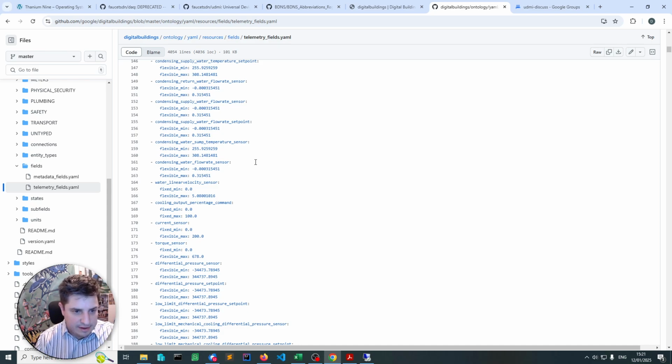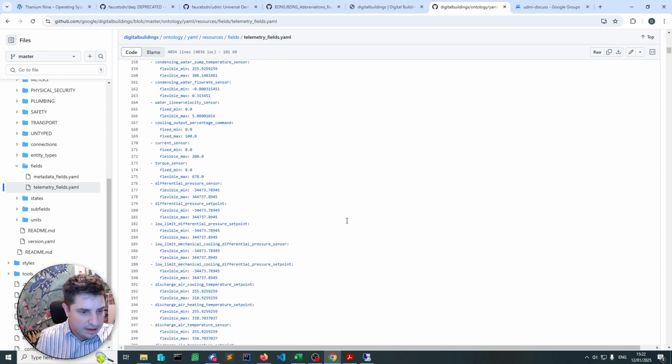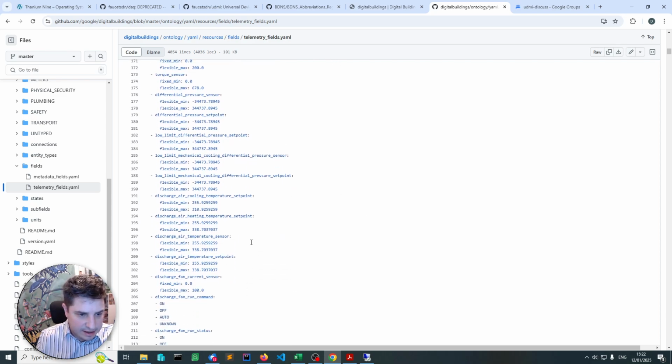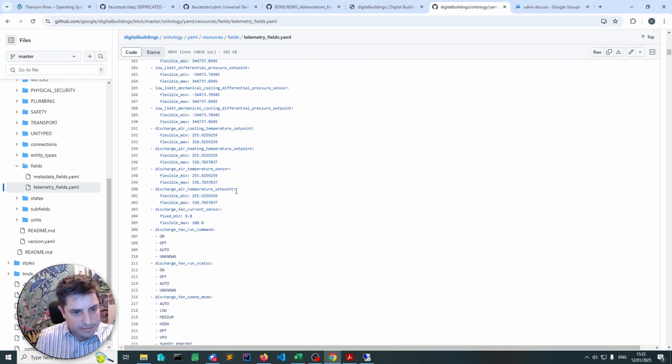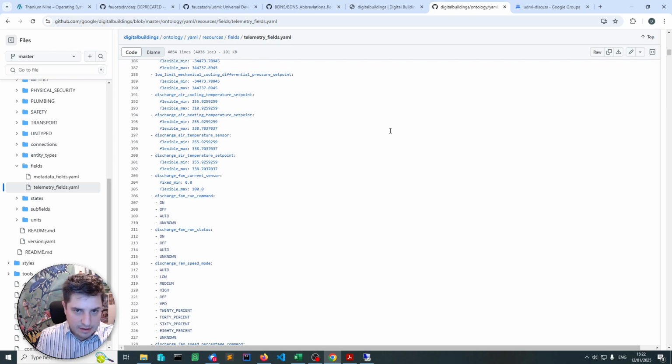Lots of different BMS companies typically have their own methodologies around point naming, and when we want to apply machine learning or standardized dashboards to systems that we want to scale, it's great if we all work off of what we call an apples-to-apples basis in simple terms. So this is a great place to come and ensure the name that you've selected for the point of data that you're going to transmit to the cloud is correctly named.